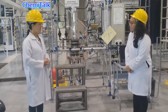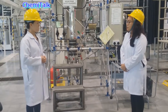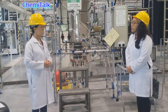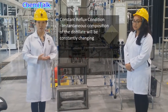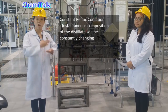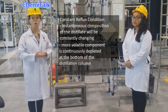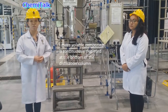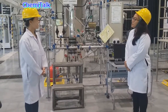Thank you for the explanation, Ms. Lee. Now we would like to proceed to experiment 2, where the experiment is carried out in the constant reflux condition. So what is constant reflux? Under constant reflux condition, the instantaneous composition of the distillate is constantly changing because the composition of the more volatile components is continuously depleted at the bottom of the distillation column. So how is the result of this experiment?